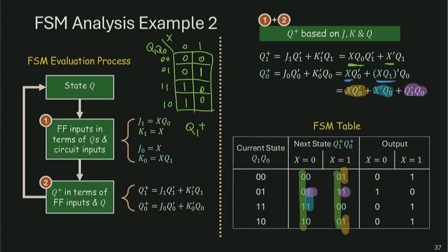This is a Mealy machine, indeed, right? As for a Mealy machine, at the output column, we would again put down the input conditions. For a Moore machine, we only have a single output column. Mealy machine, we also put all the input enumerations over here. And we can also see that from the output equation. The output depends on the x input. Right? In general, this table, you can also scale it to a 4x4 K-map. If you have like 2 states and 2 inputs, you have 4 columns over here, 4 columns over here. Right? If I have like 1 state, 4 inputs, you probably have 2 rows over here and then 4 columns over here. So you can just think of it as a different way of writing K-maps. Yeah, any other questions?